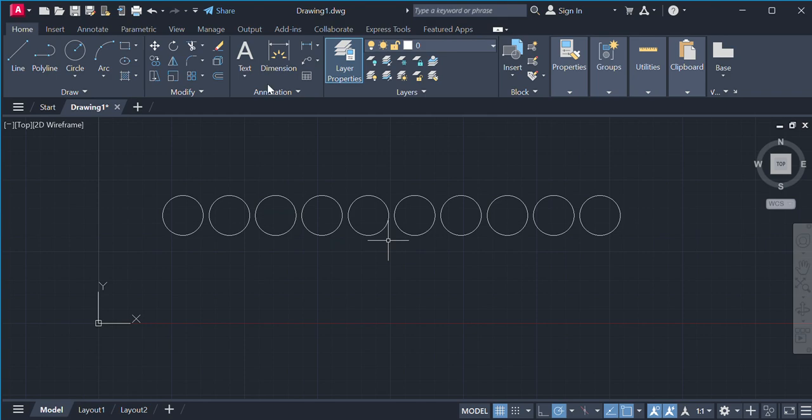Then on here, you can decide whether you want a specific layer to be plotted or not. In the previous versions of AutoCAD, we had layer 0 and we had def points, I think. And I think def points was set not to print. Not too sure about the layer 0, but what I know is a layer that's already there is a layer you want to avoid. Even though it's set to plot and print, it might plot and print, but I'm just recommending that you set your own layers. Previously, there was a def point, and once you get to your layout, then you wouldn't be able to see it, or once you print your work, then everything would be invisible, which is not what you want.